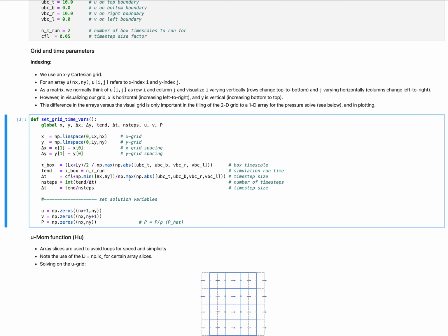Now that we have the delta t, the number of time steps is just the runtime divided by dt, but that won't be an integer, so we force it to be an integer. And then we recalculate delta t based on the runtime and the number of time steps, just to force consistency between having an integer number of time steps and a delta t that fits in t end with those time steps.